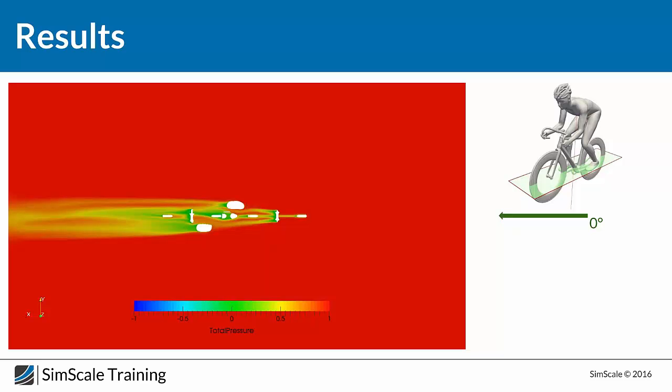Yeah, I think one point is very important, which you mentioned, the turbulent boundary layer. A lot of people get confused. A turbulent boundary layer or laminar boundary layer is not the same as turbulent or laminar flow. Here we're just talking about the flow near the surface. If you want an idea of the difference, just imagine a laminar boundary layer is made of parallel layers of air moving, while in a turbulent boundary layer you have some mixing inside, an increased impulse exchange in the y-axis.